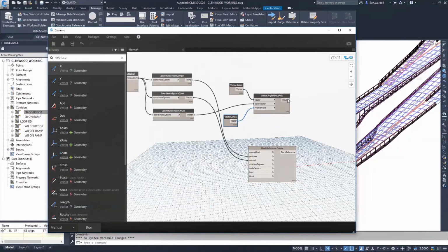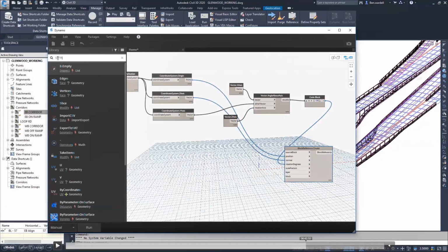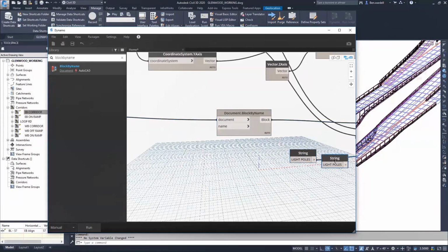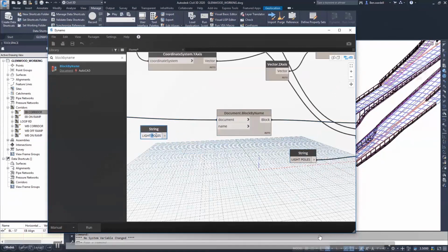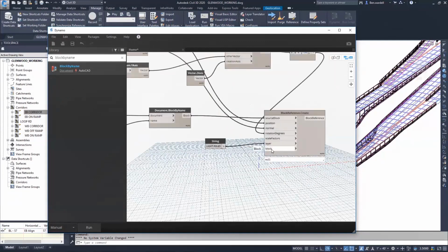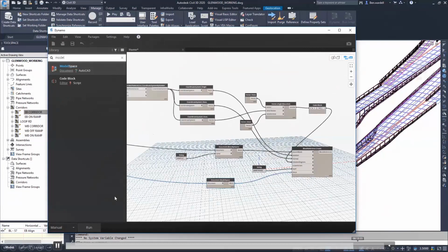Once you are done with your complete script, you just click to run. When you run it, you will automatically be able to see a number of street lights being placed within our corridor at the specified spacings. Remember I mentioned that you can use a slider to automatically adjust the spacing, which basically controls the number, or you can use a specific value.